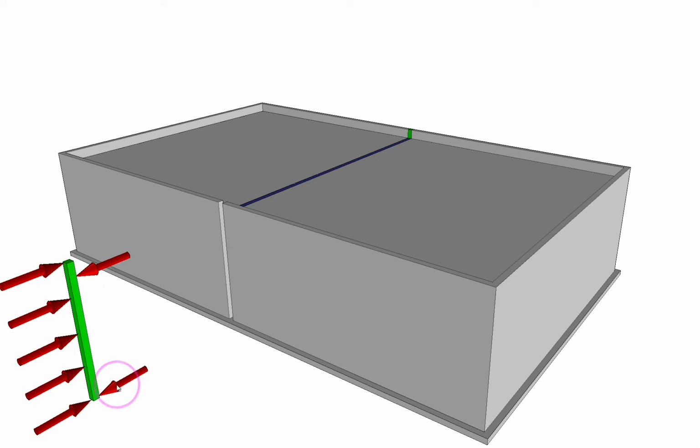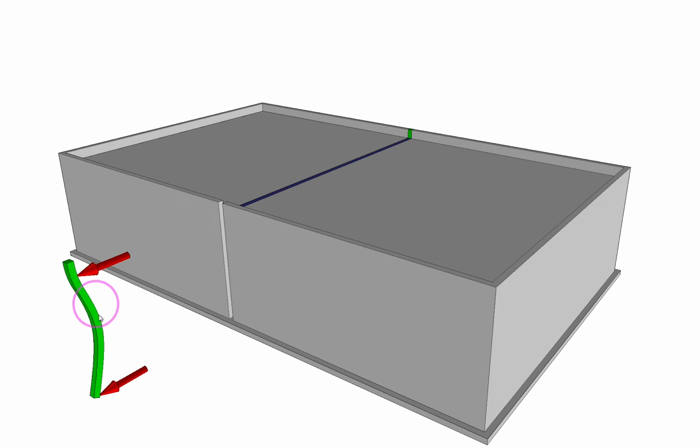So we see the wall has a support at the base down here because of the foundation. Then we have a support at the roof and our little bit of parapet sticking up on the top. And this becomes a 1 foot wide strip, and the depth is whatever the wall thickness is. And that load is an area load over here in terms of pounds per square feet. This becomes pounds per linear foot because it's a 1 foot wide strip. And that load causes that wall element to span and bend between these supporting points, just as though it were a regular beam.